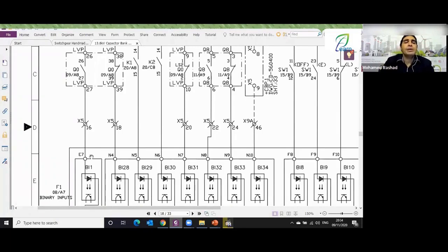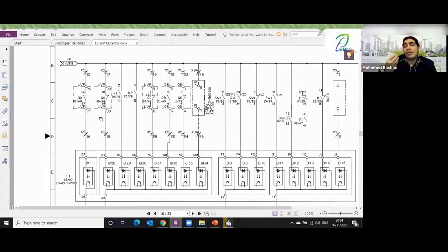All right, very good. So we agreed that the motor of the breaker is depicted in a state where the spring is charged. The MCB, the auxiliary relay, the contactor, and the lockout relay are all in a de-energized state. And the breaker is depicted in a test position and is shown as open.